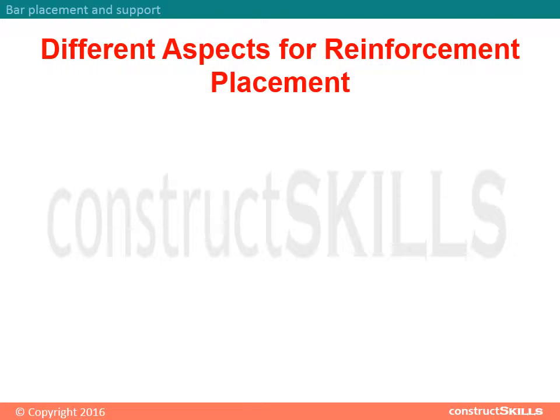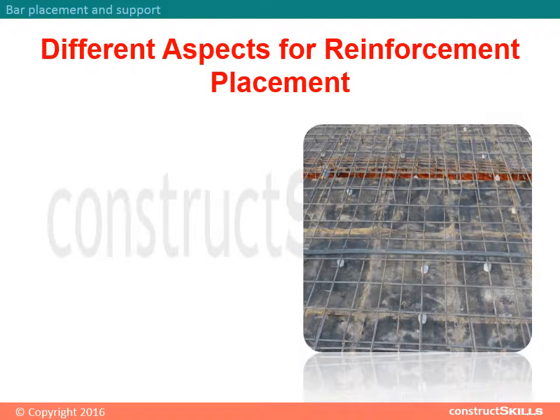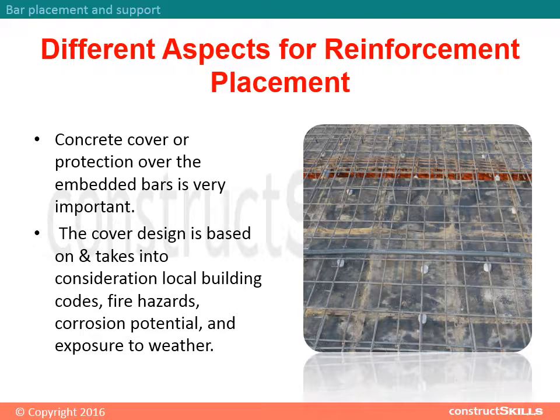Different aspects for reinforcement placement are: concrete cover over the embedded bars is very important, and the cover design is based on and takes into consideration local building codes, fire hazards, corrosion potential, and exposure to weather.